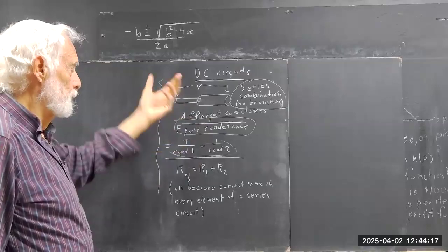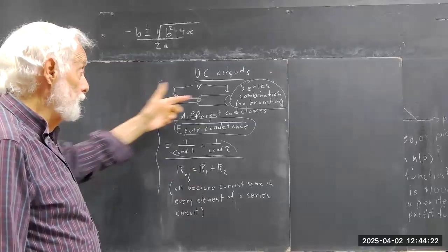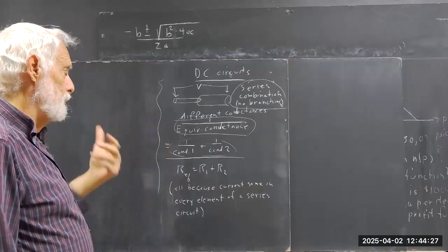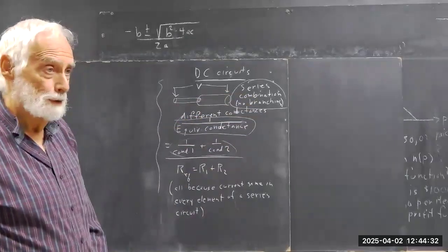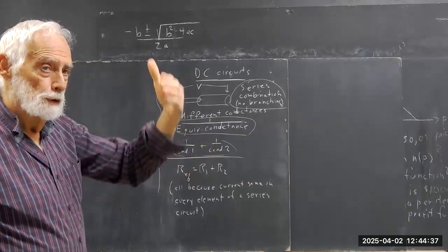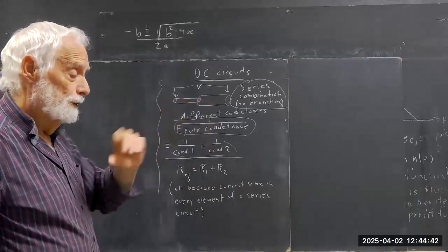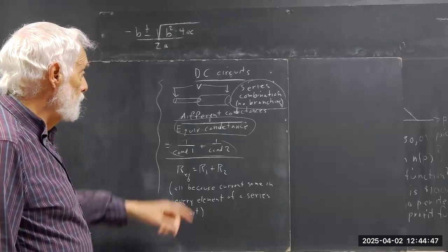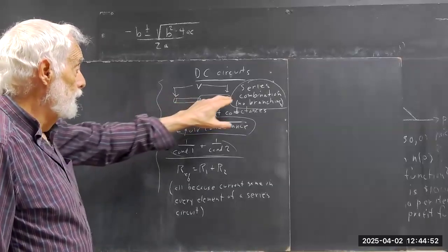Analogy would be these are two cylinders that are conducting heat. They're insulated, so no heat escapes the sides, and the heat to travel through these things has to travel in a straight line. It has to travel through cross sections. Okay. And the heat flow will then be perpendicular to the cross section. In that case, you have an analogy that you've got a heat current. Okay. So then what drives the heat current is the difference in temperature between this end and this end.